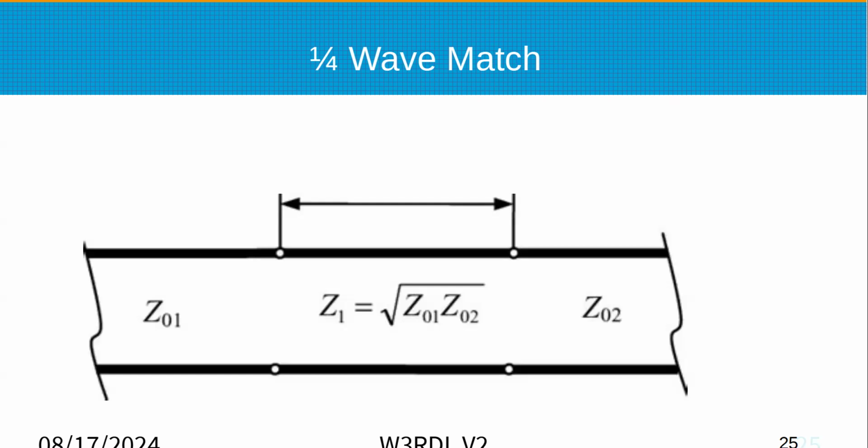Well, the only way it could affect the bandwidth is if it affects the Q, and I don't think it would, because all you're doing is matching the impedance of the antenna to your feed line. So it has no effect. It shouldn't have any effect on the Q of the antenna.